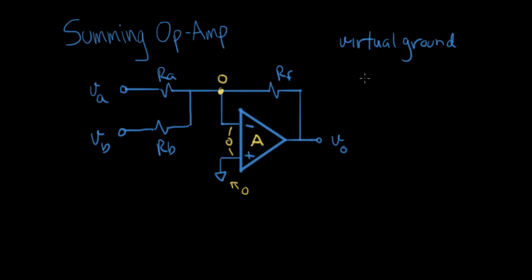So let's move ahead and analyze this circuit. What we want to find is V out as a function of VA and VB. Looking at my circuit, the other thing I know about op-amps that's always really important is that the current going into an op-amp input is 0 or practically 0, and for the purposes of what we're doing here, we can treat it as 0. So we have 0 volts on this node, and we have 0 current going this way. So let's go after this current right here. Let's figure out what that is. We'll call that I.